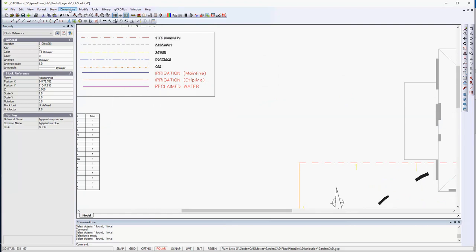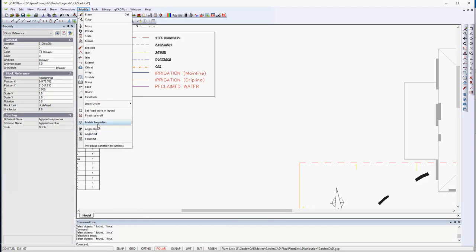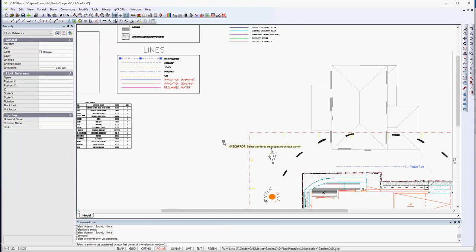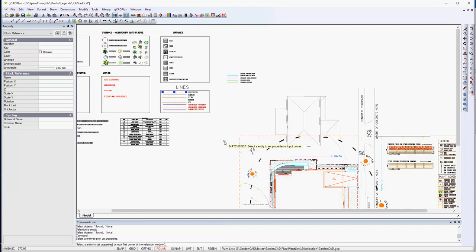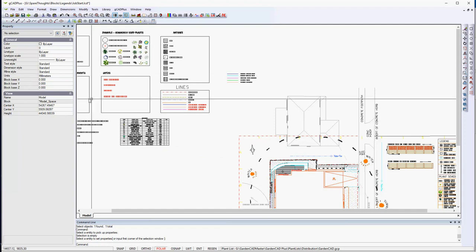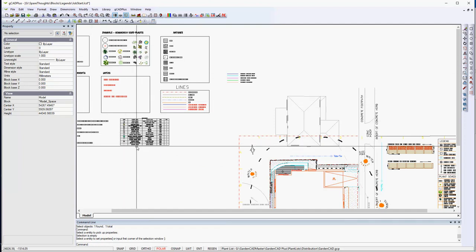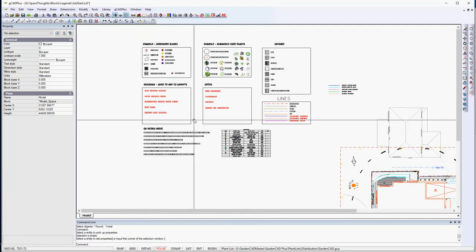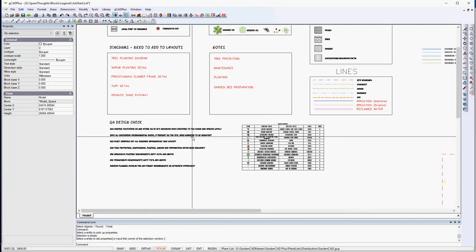and I was hoping to be able to use modify and match properties on my right click, the next time I try it I'll have it there, but I can select the site boundary line there and then just apply it to the site boundary. So you can match the properties of anything in the little area here and apply it in the design. So the template with a whole series of prompts and commonly used entities enables the generation of that design quickly and easily.